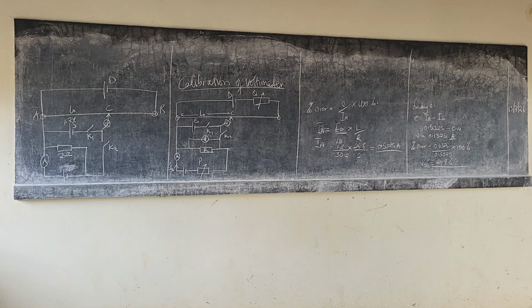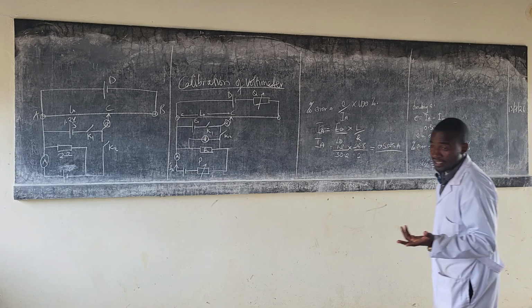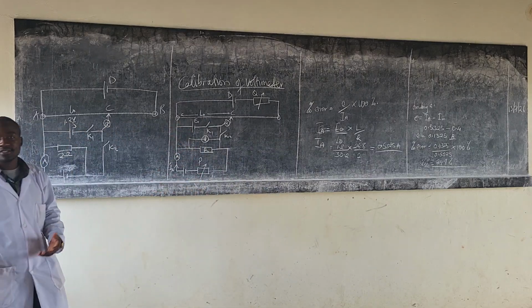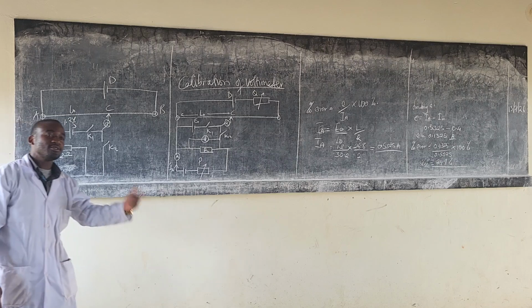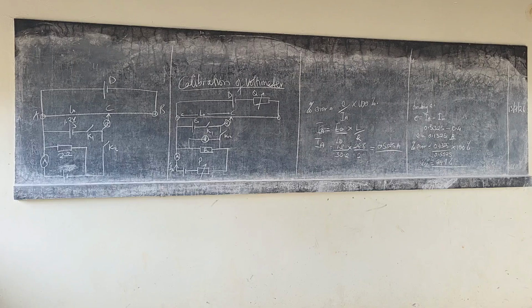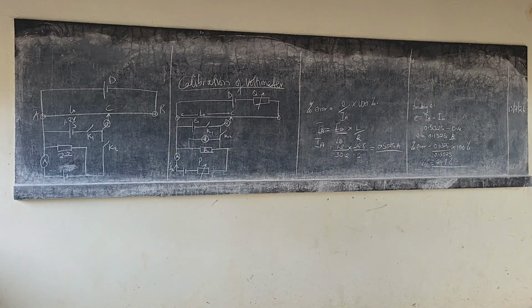One thing that most of the times makes it a little complicated is the many components that are put in the circuit, and you end up not talking about them. For example, in the previous circuit, we had a variable resistor, Q, and even here we end up not talking about it. But in the calculations, that's when you see its meaning, whereby you're supposed to find that constant current that flows through the slide wire that will help you get the PD per centimeter.